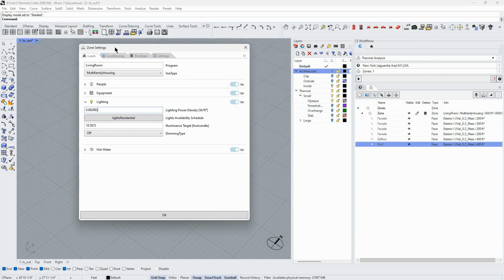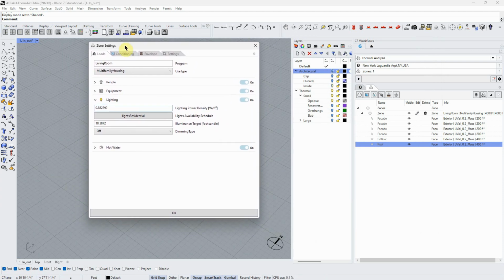And so these are things that, once we've decided this is the level we're going to be at, we would set them to these specific levels and leave them and iterate other things that are more architectural. But we still need to know what they are so that we can determine if we're meeting our end goals, which is going to be some standard that we've defined. In this class, for example, Local Law 97 is what I'm saying that we're going to make our standard for energy usage, and that's because it's what we have to do in New York City right now, and it's pretty stringent. So anyway, we would schedule our lights when they're on.